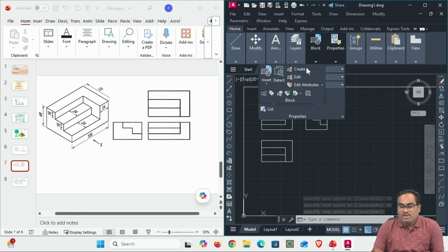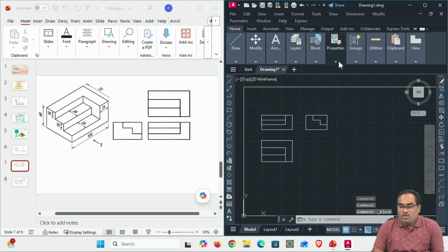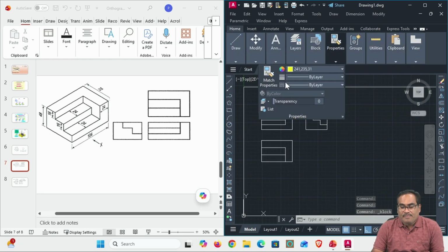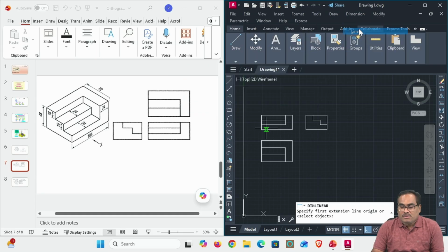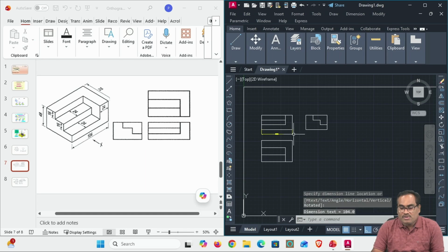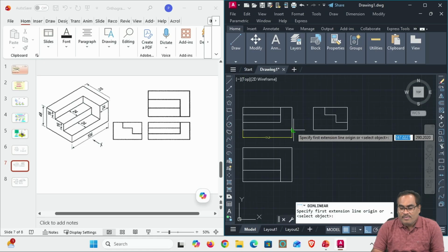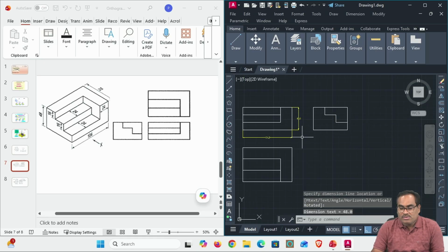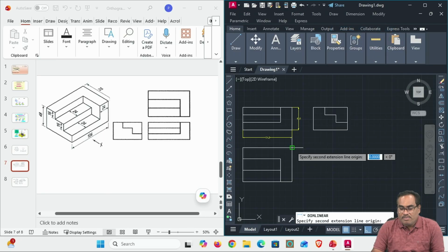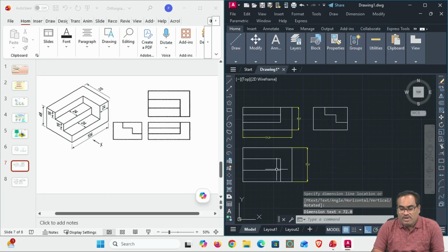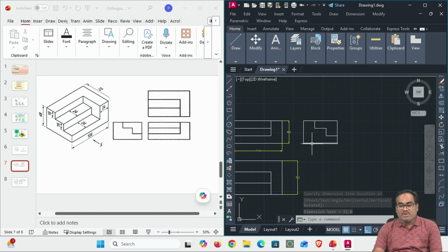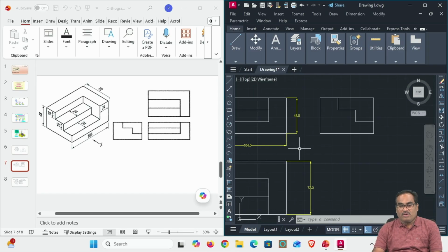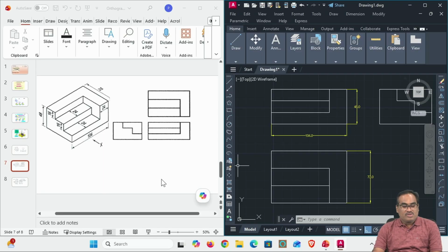Okay, if you want to keep the dimension, you can, no problem. Go to properties, take a different color, and then linear. So whichever you want. So in the front view you are able to see 104. Keep this 104, and the front view height, you are able to see height also. This side height also. Okay, right. No need to repeat. So this is already 104. Again, you need not give it. So something like this you can give the dimensioning. Okay. So this is how it looks. Front view. Very easy. So I'll take another one. So like this, you can draw any complicated figures also.